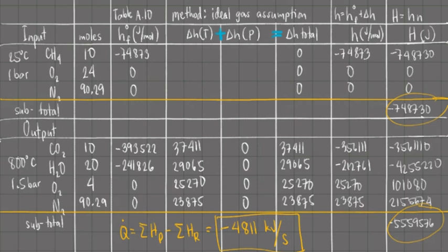What's important for you to understand is the process on how we determine the actual absolute enthalpy of each of the substances and how we add them up in order for them to be incorporated in our first law of thermodynamics analysis. Okay? Please do watch out for other videos detailing specific examples and specific applications of this first law analysis for reacting systems. This involves more systems on combustion, particularly determining the adiabatic flame temperature, as well as its application in liquid phase reactions.